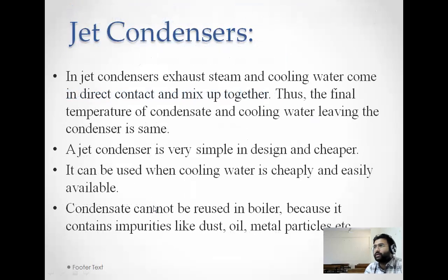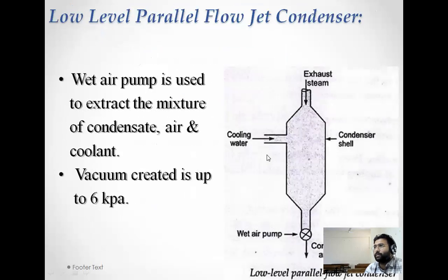In jet condenser, we have seen types. This is a parallel flow. This is a low-level parallel flow condenser because both the steam and water are flowing in the same direction. That is why the name is parallel flow.